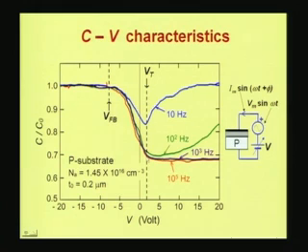which is called the threshold voltage denoted by the symbol Vt. The capacitance falls, and at high frequencies the capacitance beyond this Vt point or threshold voltage point saturates. At very low frequencies of about 10 Hz or lower, however, the capacitance rises again, okay, to the value that you had for very high negative voltages. Now this is the characteristics assuming a p-type substrate.